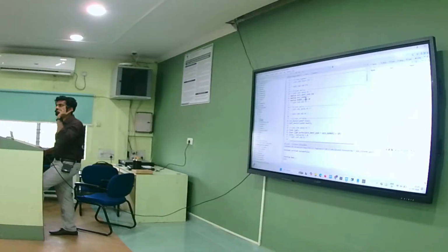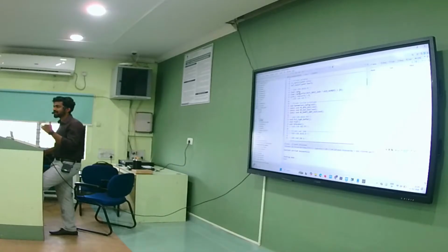You will train your model for 40 cycles. And also here the same variable; one more extra variable will come. Three functions: void fill buffer, void train, void inference. Then in user code begin, for this function void fill buffer, we fill the buffer with sample data. For loop we create from 0 to 256.